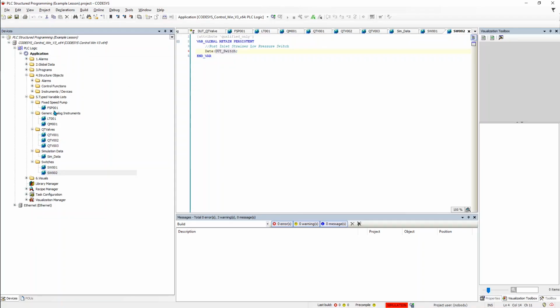So these would be accessed by all areas of the code in terms of control and in terms of interfacing from SCADA. And that really plays the first part of building the project. So once we're at this point where we have our structures declared and the structures are actually being used and tied against a variable, we're now ready to have a place where inputs can be mapped to, SCADA interactions can be mapped to, and then control statuses and elements required around the general control of the PLC program have a place in which they are going to be stored.